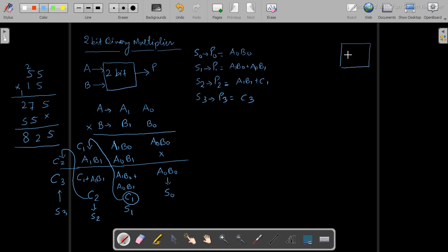If you want to design a 2-bit half adder, we require two inputs, that should be 2 bits. Say for example that the bits are a and b. After adding these two inputs, we'll get the sum, and if there is a carry, you get the carry out. After designing the K-map and implementing the logic, we came to know that for the sum, we can use the A XOR B gate for designing the sum logic. For the carry out, we can use an AND gate between A and B.